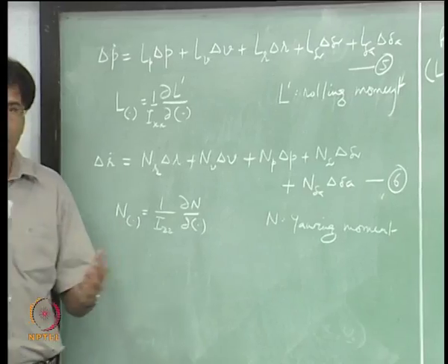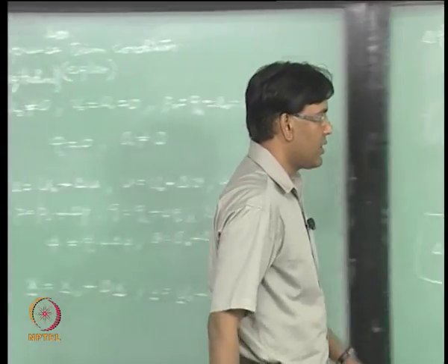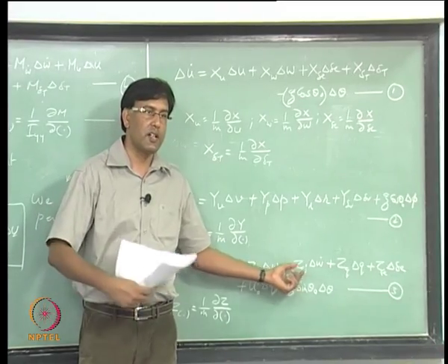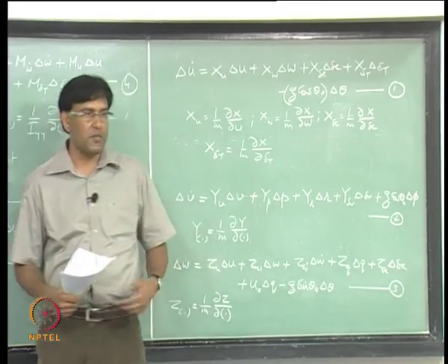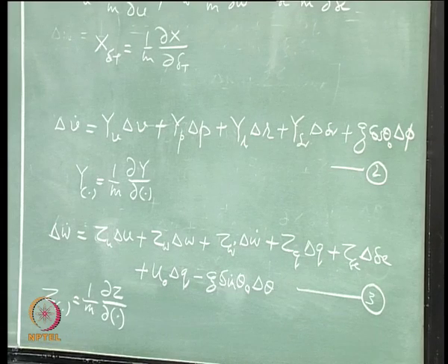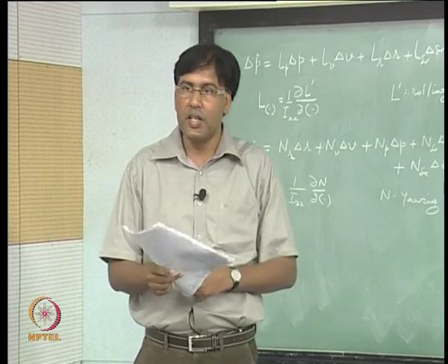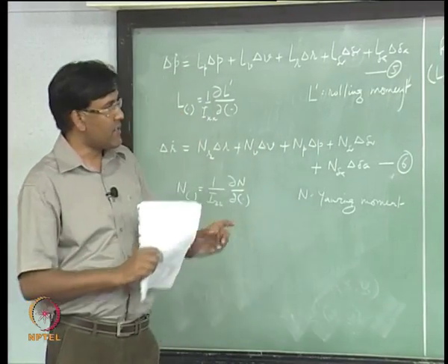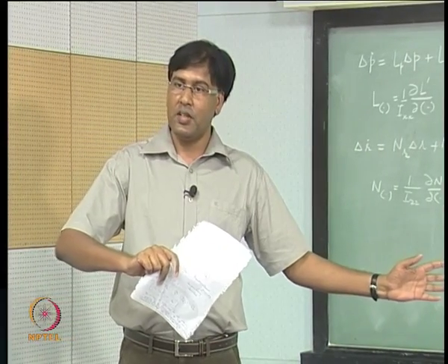Remember to simulate the accurate motion of aircraft. If my wind tunnel measurements give me this as I am measuring, and this is not a small value, then I have to include that in the equations of motion. So, whatever data comes to you from the wind tunnel measurements, you have to keep it as it is, and then you have to write down the equations of motion accordingly, whether it is perturbed equations or the full form of equation. So, you have to write your equations of motion in such a fashion that you can include all the data that is provided to you, and this data is coming from experiments.